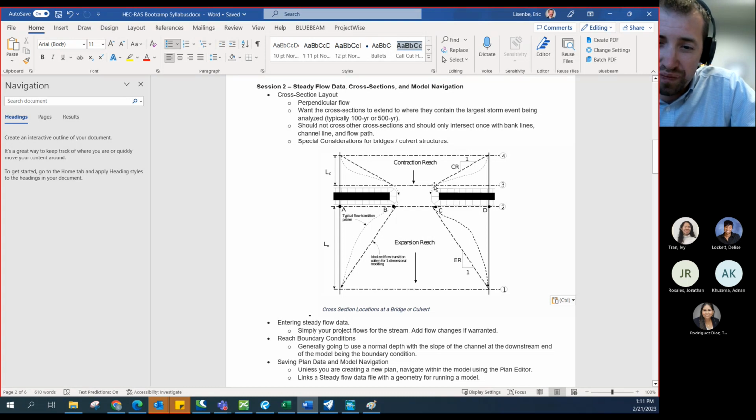So when you're figuring out how much you need to go for your next cross section, a lot of times it's not critical to be to the nearest foot. You want a cross section right at the bridge face, and then you want one slightly upstream of it where most of the contraction will have taken place. And we'll talk about this a little bit more when we talk about ineffective flow areas later this week.